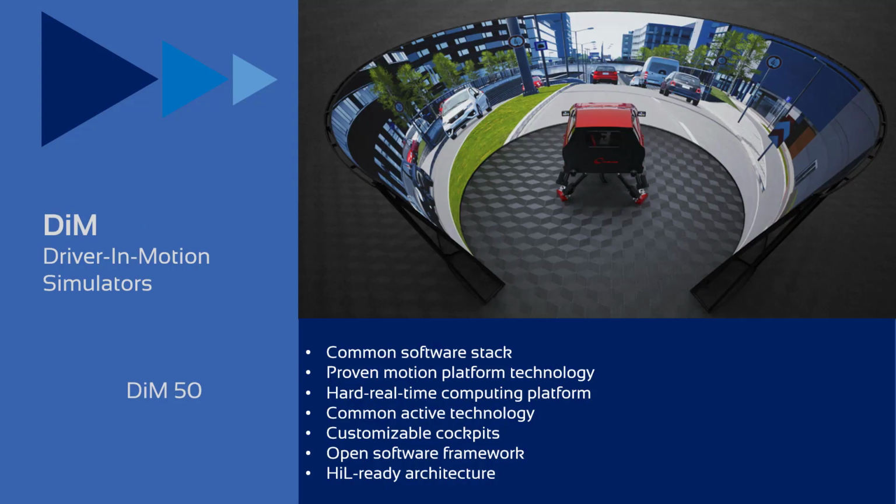VI-Grade's flagship dynamic simulator platform is DIM, or Driver in Motion, which uses the same modeling solutions for vehicle dynamics, traffic, and sensors that we already covered. The DIM platform starts with a 6 degree of freedom hexapod solution of the DIM 50. This is an excellent solution for ADAS and HMI applications where onset of vibration response is critical. For example, transition from automated to driver control where the first cue of the driver is a dynamic braking or steering cue.